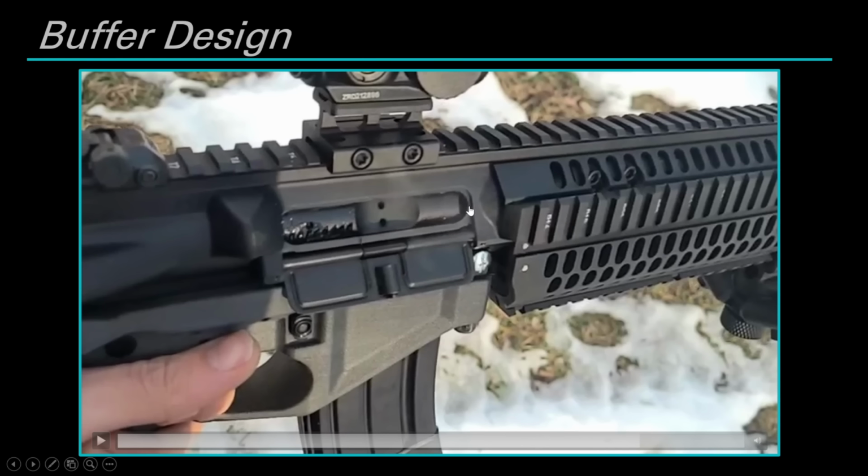However, if the bolt carrier then is capable of bouncing backwards, the bolt carrier will have the firing pin retract as the hammer is coming forwards, and the hammer will smack the firing pin while the bolt carrier and firing pin are in this retracted state. Because of this, the hammer will push the bolt carrier forward, but the firing pin won't come forward with enough force to fire the primer.